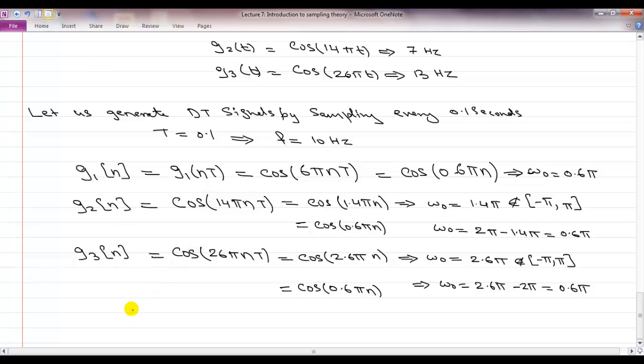So the discrete frequencies, if you remember, do go from minus infinity to infinity, but the only unique part is contained between minus pi and pi. So there is a wraparound of frequencies that happens. Minus pi, pi. Now, this whole region is then repeated again and again, up to 3 pi.